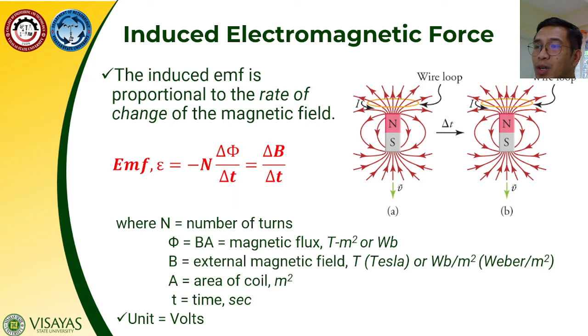The energy added per unit charge has units of volts. So, the electromotive force is actually a potential. However, unfortunately, the name electromotive force has stuck, and with it, the potential for confusing it with a real force. For this reason, we avoid the term electromotive force and just use the abbreviation EMF, which has the mathematical symbol epsilon, or lowercase epsilon.